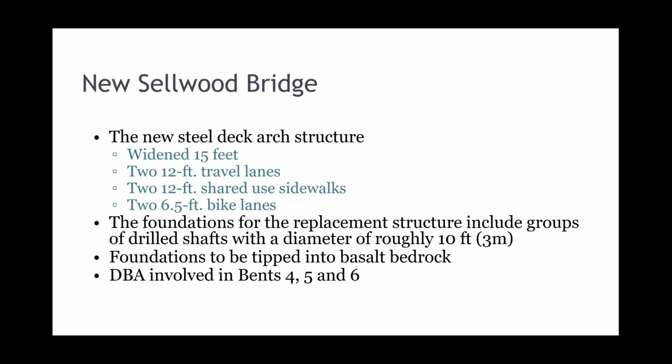The existing structure, which was 80, 85, 90 years old, was actually moved laterally onto a temporary pile bent system. And that existing structure, although put onto a slightly new alignment, did have to remain in service during the entire construction. So take a really fragile old bridge, move it laterally 20 or 30 feet, and keep it open during major bridge construction was no small feat.